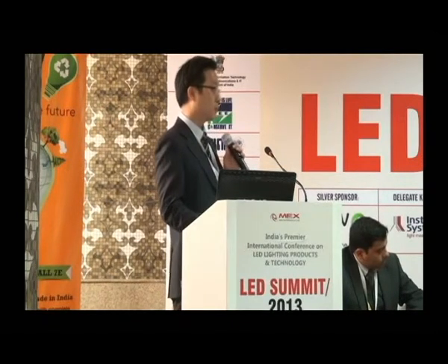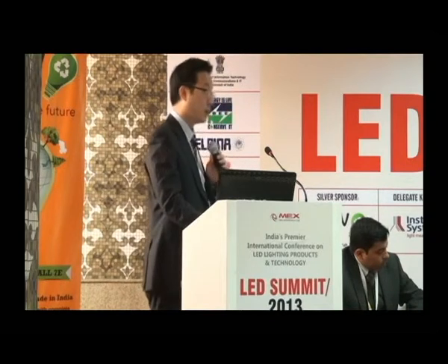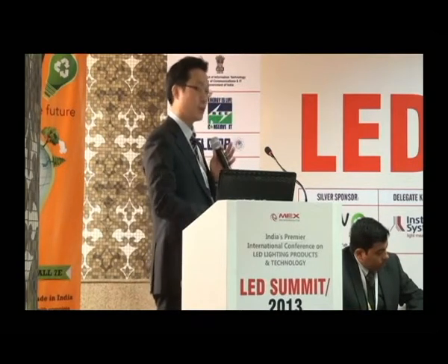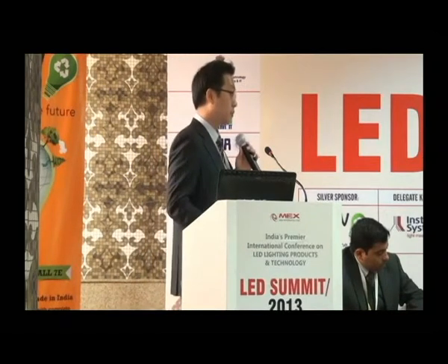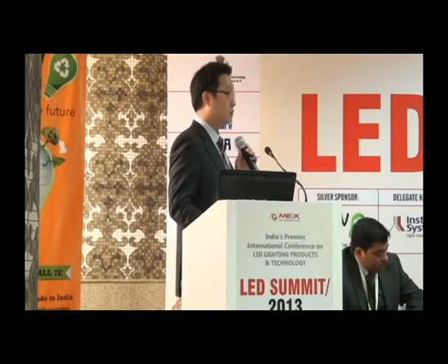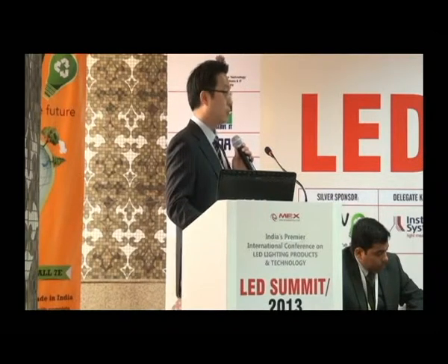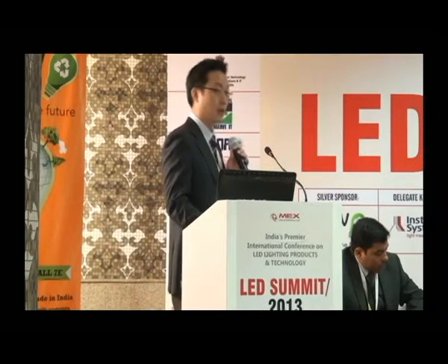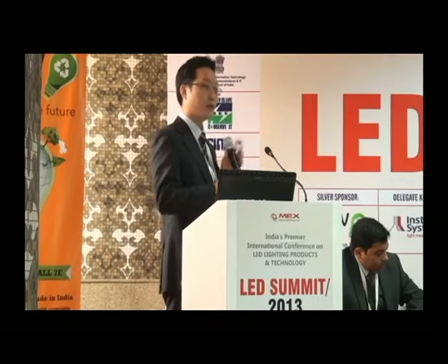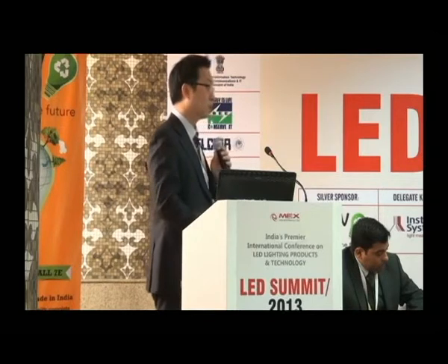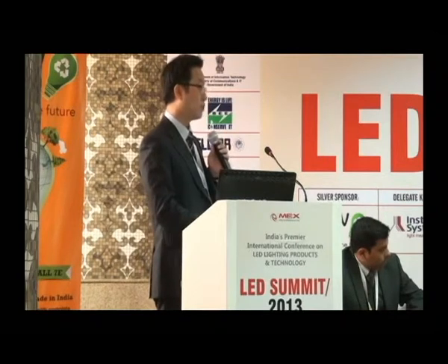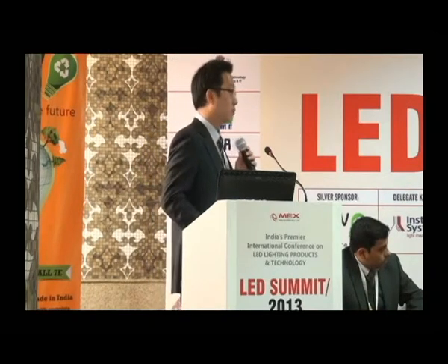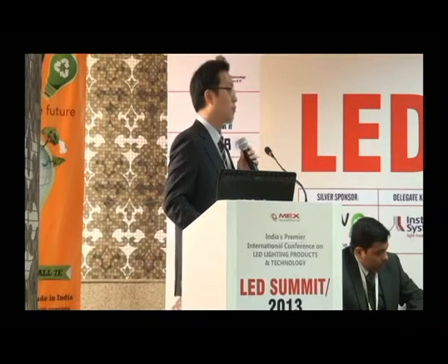That is the reason why customers have to mix the phosphor or some coating, or sometimes some alternate phosphor layer is needed to convert this blue light to yellow light. So the blue light together with the yellow light can make white light. Sometimes customers use red or green, but the yellow phosphor is the main material to make white LED.